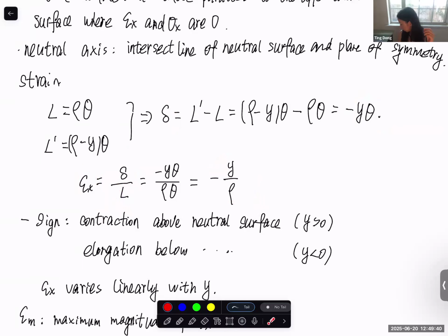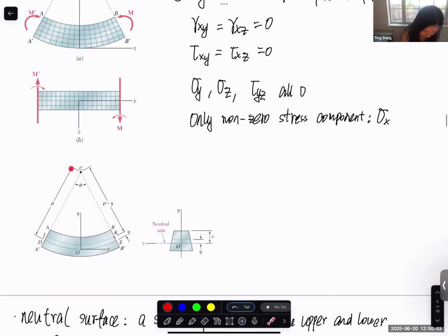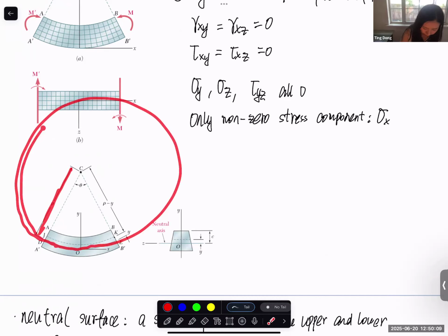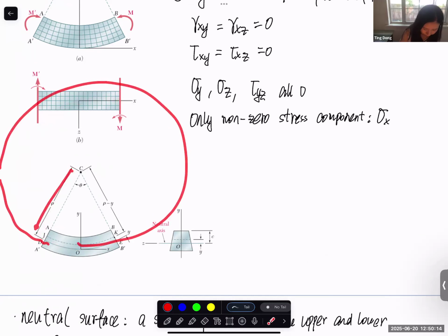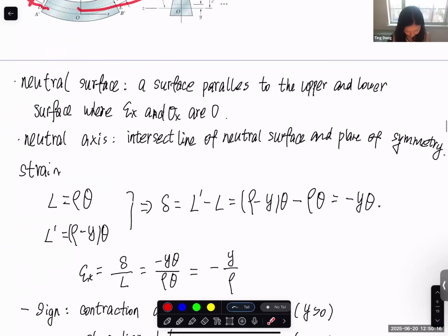curvature. So basically, you can imagine that when you bend a beam, this arc is a part of a circle, and the radius of the circle, if you calculate from the neutral surface, becomes the radius of curvature, and this is rho here. If you see in the graph, this is the rho. If you consider the beam bending, it's just an arc, and if you put a full circle here, there's a radius. So that is the radius of curvature of the beam bending.